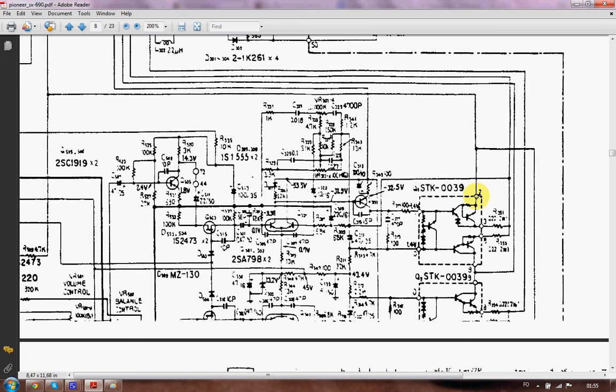And if that's okay, and you read with your oscilloscope on here, and you get a signal in, but you get nothing, no signal or voltage out at all, you can almost say for 100% that your amplifier is gone. But if you have no sound at all, there's probably not going to be something wrong with your amplifier. Because if there's something wrong with your amplifier, the amplifier is split in two channels, as I talked about. You have a right channel and you have a left channel.